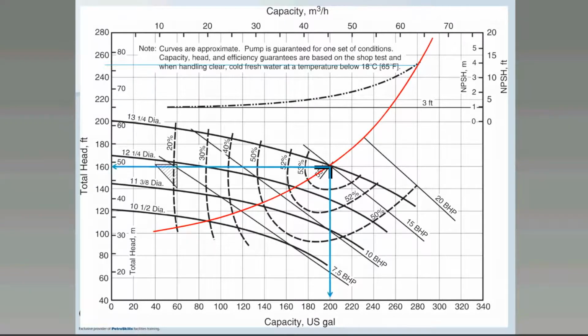And then if you remember, our flow rate actually came up at about 280 GPM. So that means that each pump is going to move 280 GPM. So you can see the operating point when we move to 280 GPM, we see the pump head drop right down. So the pump head is now reduced from 160 down to around about 125.